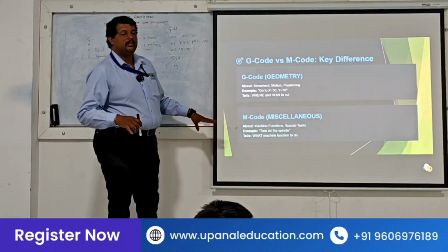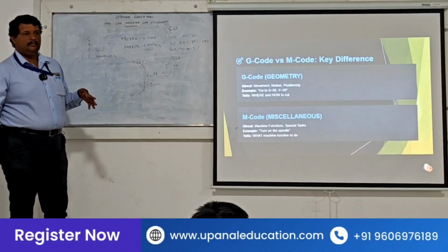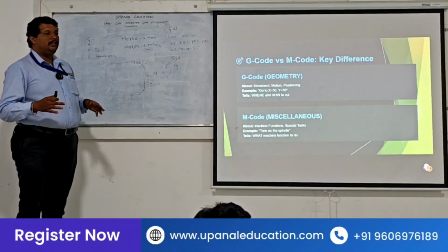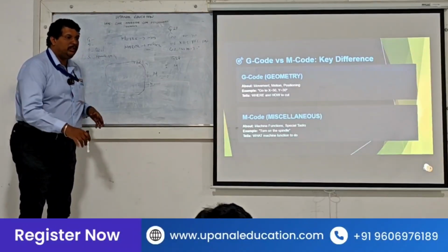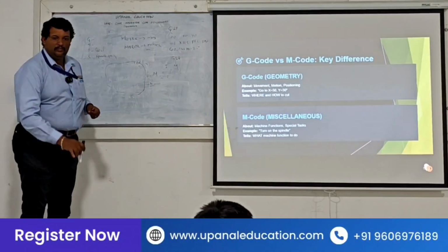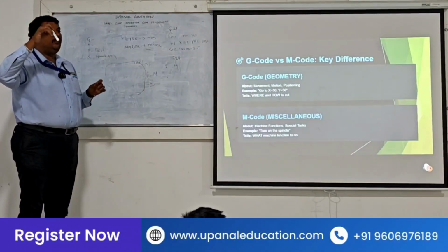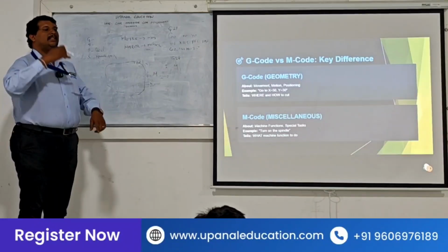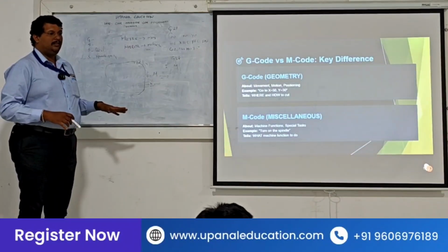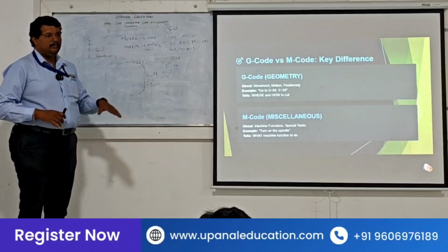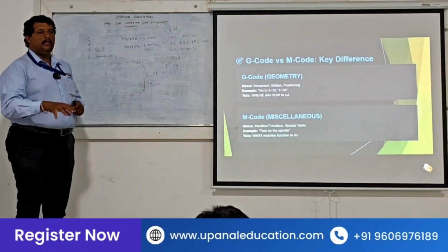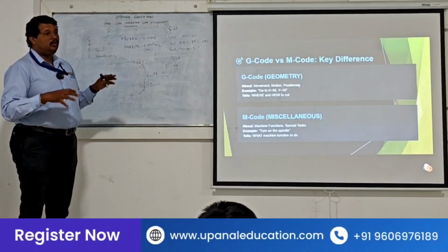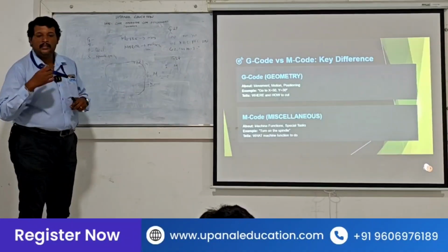For example, if you go to exhibitions, like our Intex exhibitions, you will see some CNC machines where the work is just being shown, it's repeating. One work will be completed, again it's repeating. So we tell the machine using the M code, once you finish the work, restart it. Don't wait for any orders. Normally, once a work is complete, the operator has to go and switch it on again. But there are M codes for automatically repeating.